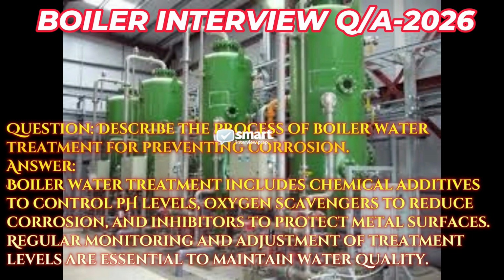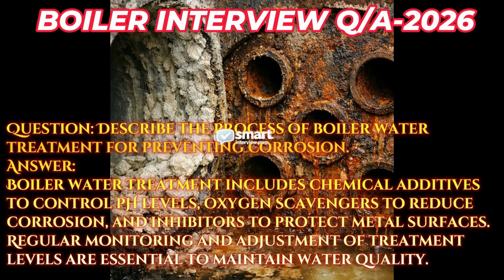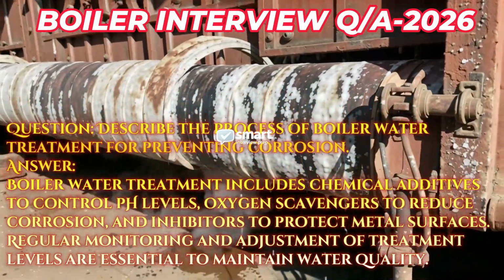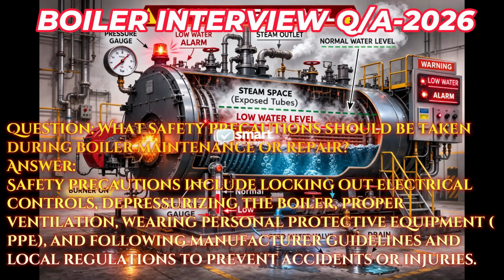Question: describe the process of boiler water treatment for preventing corrosion. Answer: boiler water treatment includes chemical additives to control pH levels, oxygen scavengers to reduce corrosion, and inhibitors to protect metal surfaces. Regular monitoring and adjustment of treatment levels are essential to maintain water quality.